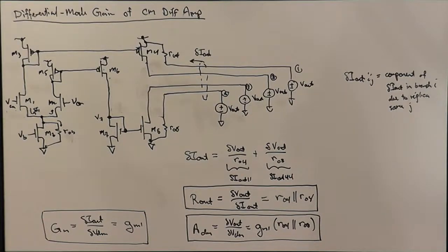And so if you try to only selectively account for things like the early effect when you're doing the common mode calculation, you wind up getting the answer wrong. You get something that's in the right order of magnitude, let's say, but it's very easy to be off by a factor of 2, 100%, or more.